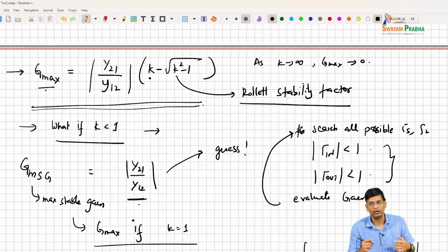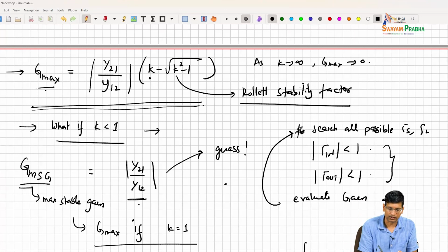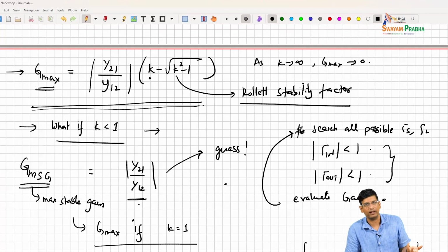Right? But when you did that, in this case, what will happen is that your network will be conditionally stable. So it will only be stable around that particular impedance that you choose, right? So you have the same problem that we discussed earlier, which is that you have stability circles that you have to work around and make sure that your device is stable. So all the simulators will give you this parameter and this parameter, right? So they tell you how well you can do.